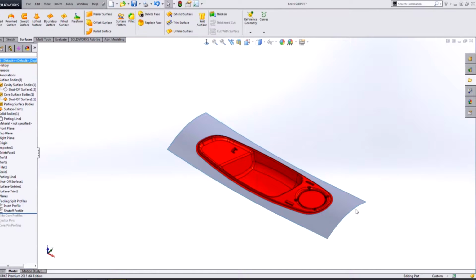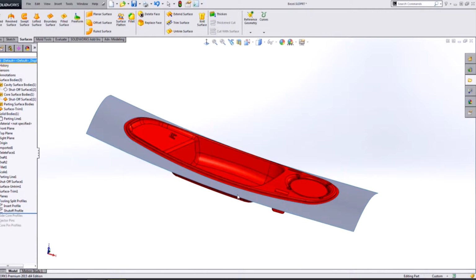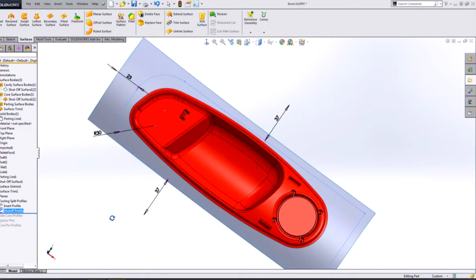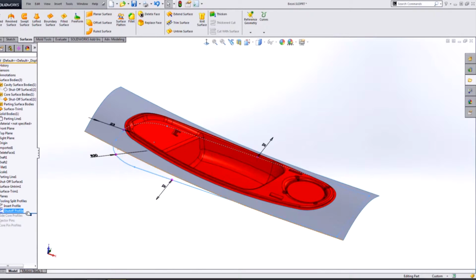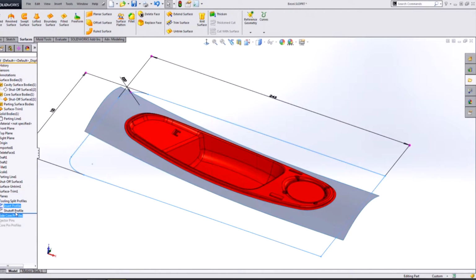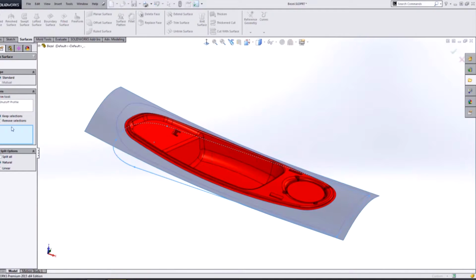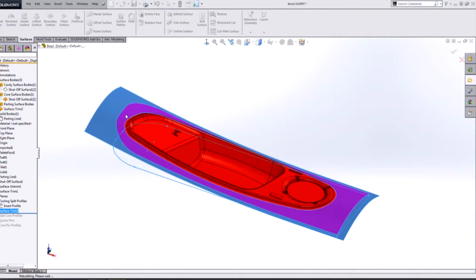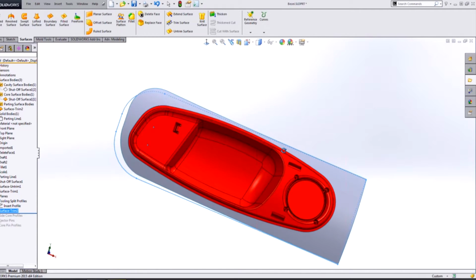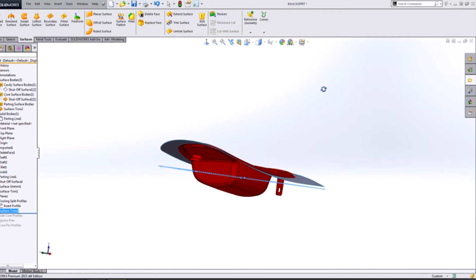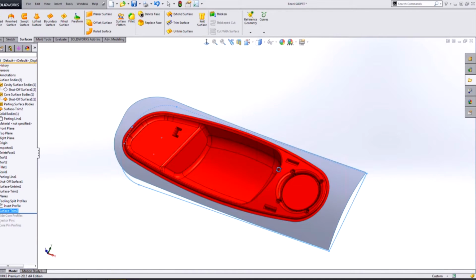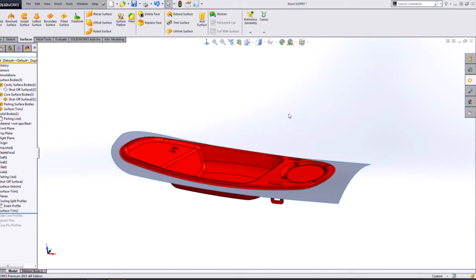If we're going to go ahead and roll forward here, what I want to use is one of these profiles that we already have here to trim this surface back to fit inside of the die that will be our mold. So we'll go ahead and use that shutoff profile there, and again turn to our trim surface and choose to keep the inside region like so. Now we have a defined shape for that bulk extra material, and we can go ahead and create now the tooling split that's going to be our mold.